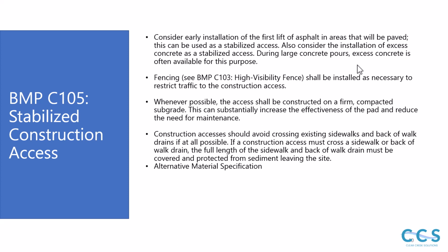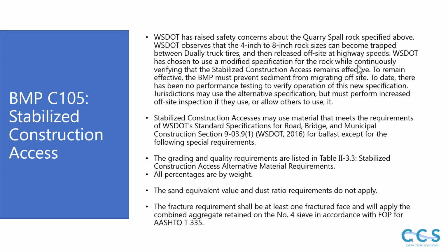Construction accesses should avoid crossing existing sidewalks and back of walk drains if at all possible. If a construction access must cross a sidewalk or back of walk drain, the full length of the sidewalk and back of walk drain must be covered and protected from sediment leaving the site.